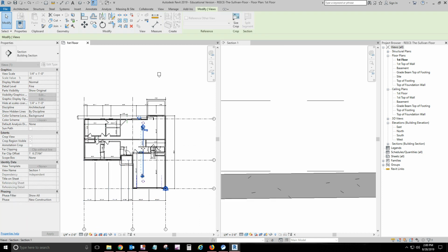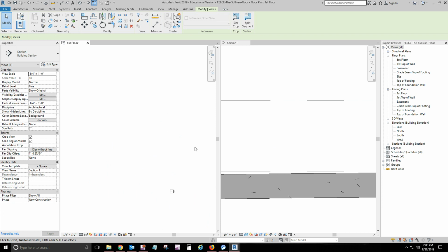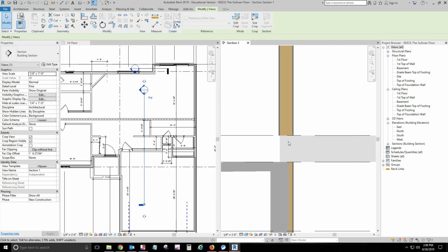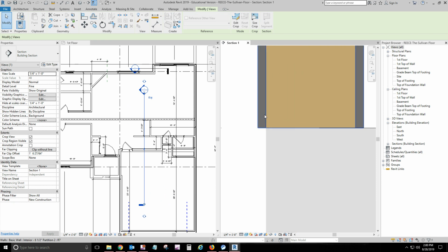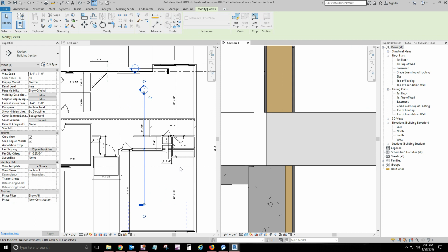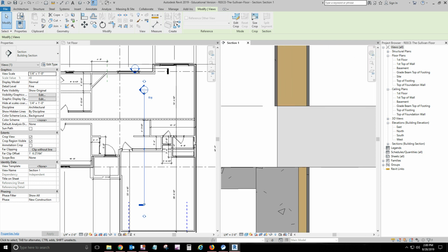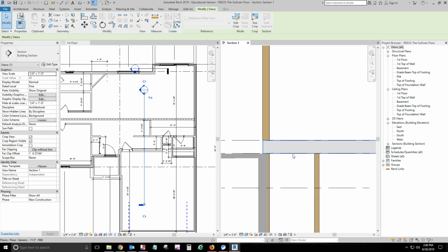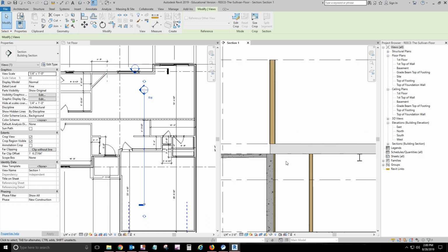When we get down to this area, it should be lined up with the outside of the wall stud. Okay, and then of course right here there is no wall. That's fine. Here we came on out to here. So it looks a little weird here, but we're going to work with it, make it work. So get this floor system in and then check it all the way around to make sure it's correct. And then we'll start on the sill plate next.